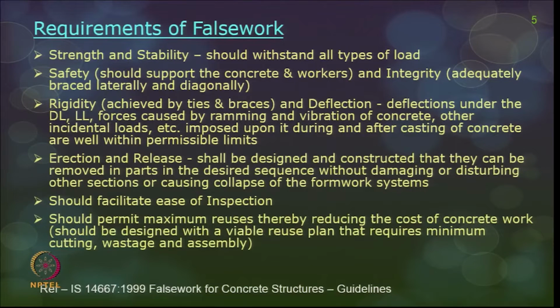And this should also facilitate ease of inspection. Wherever inspections are planned, it should have maybe a small window or something, so that you can actually inspect the concrete if you want to. It should also permit maximum reuses, thereby reducing the cost of concrete, and should be designed in such a way that it requires minimum cutting, wastage and assembly.